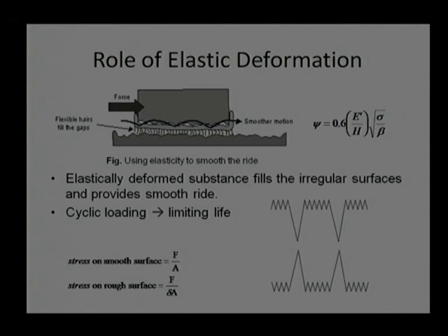That will be continuously decreasing. A component can tolerate much lesser stress at a high number of cycles. So almost all the components other than iron will have a limiting life. If I am using any lubricant, that also will have a limiting life. That is why we need to replace lubricant frequently or depending on duration, maybe after 10^6 cycles, maybe 10^10 cycles, for which it was designed.